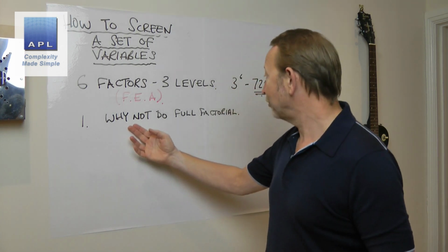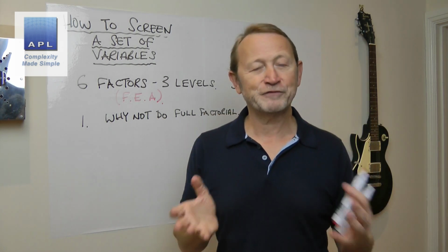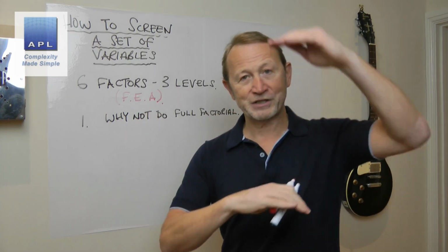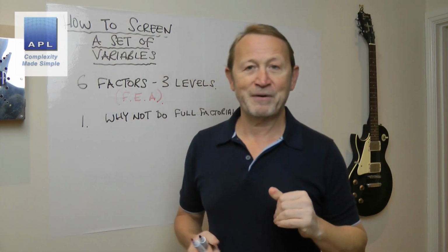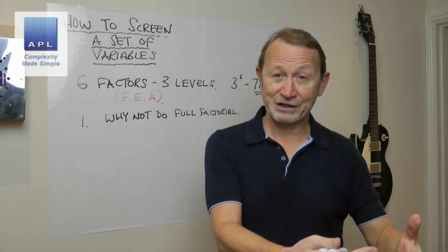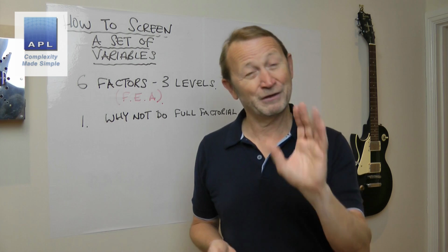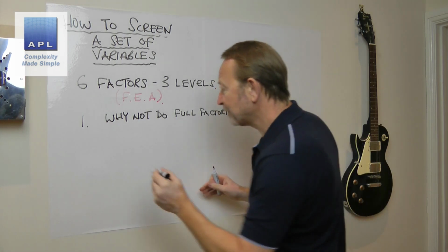So on a computer, doing full factorials with lots of combinations is often okay. Sometimes the FEA software allows you to take a pattern, maybe in an Excel file, and load that pattern in, and then run the results overnight. You come in the next day and the data's there. So doing the full factorial might be an option. All right, so that's suggestion number 1 for you.